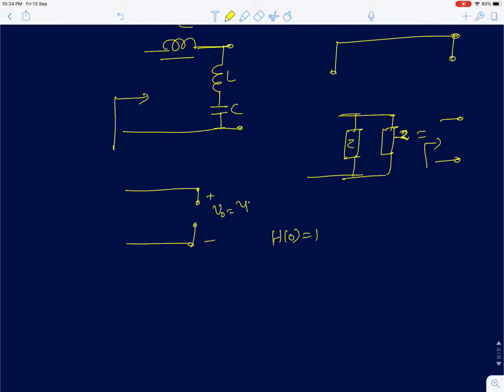Next you have to find the 0. To find the 0, there are two conditions. One, the impedance Z2 becoming equal to 0. That happens when SL becomes equal to minus 1 by SC. This impedance here, when SL becomes equal to minus 1 by SC, a series LC circuit offers 0 impedance at the resonant frequency. Again, we already discussed this in the previous lecture.